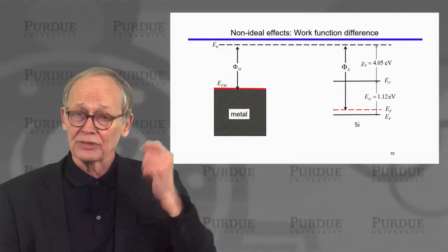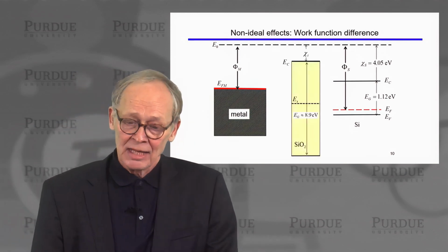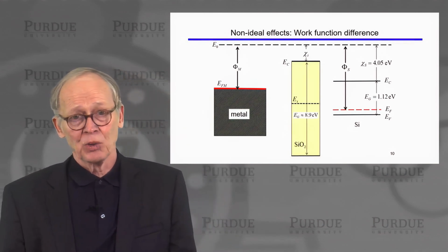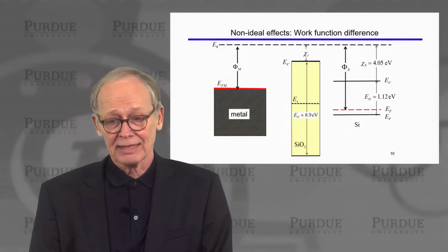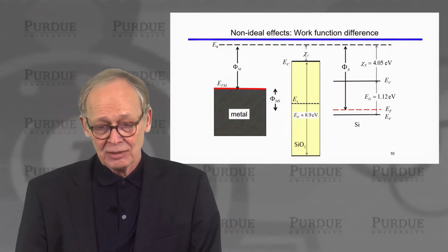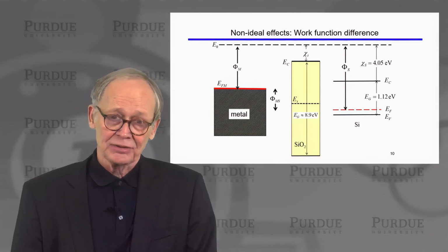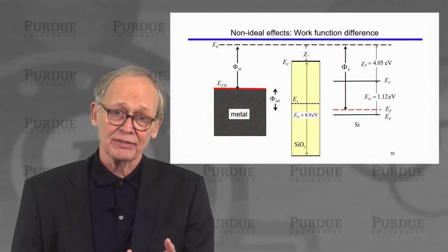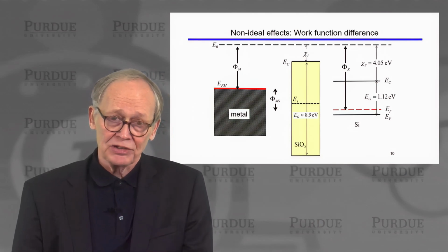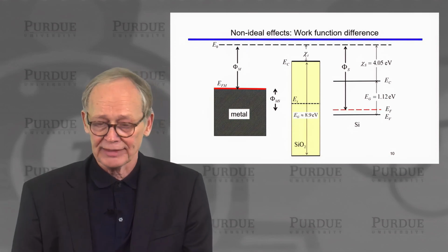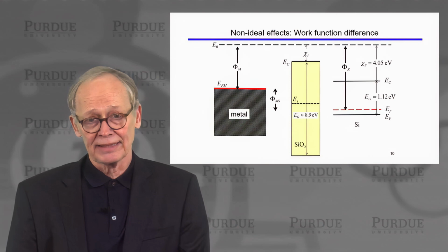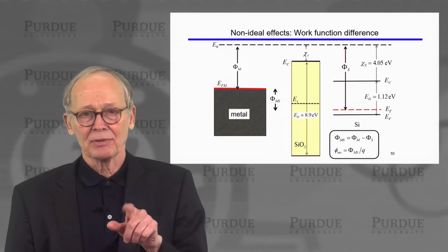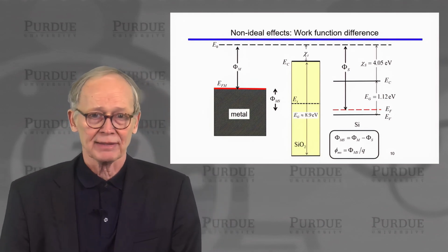And the chances are those two work functions are not going to be the same. When we put this metal, insulator, and semiconductor together and we're in equilibrium, there has to be one Fermi level constant everywhere. How is that going to happen? Well, that happens because a positive potential develops on this gate, a built-in potential there, even in equilibrium, which lowers the energies in the metal gate, pulls this Fermi level down so that it aligns with the Fermi level in the semiconductor. So that metal semiconductor work function difference, capital phi sub ms in joules or expressed in electron volts,